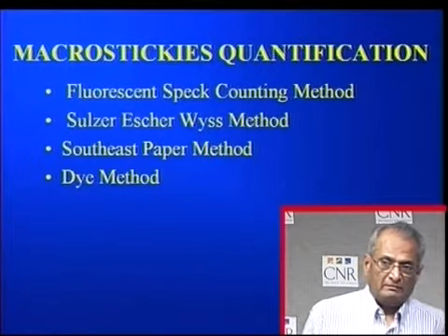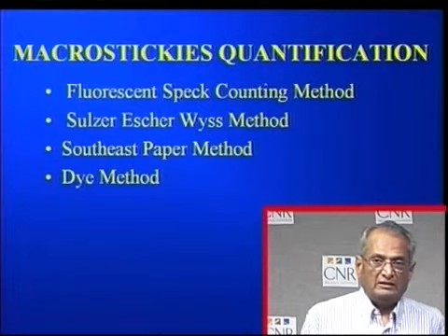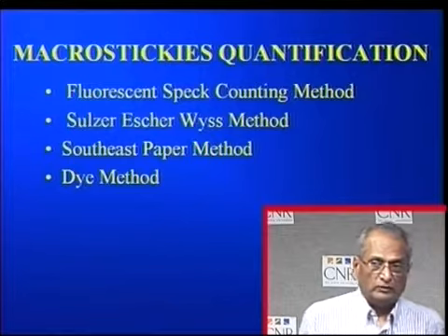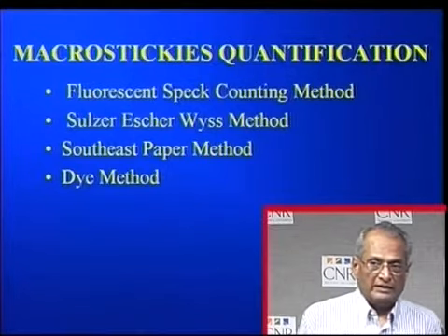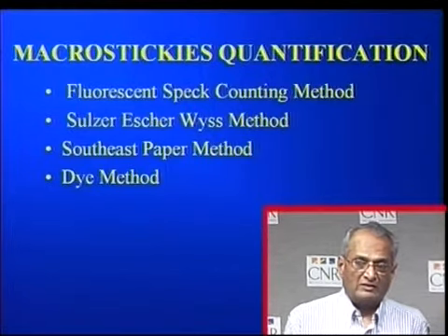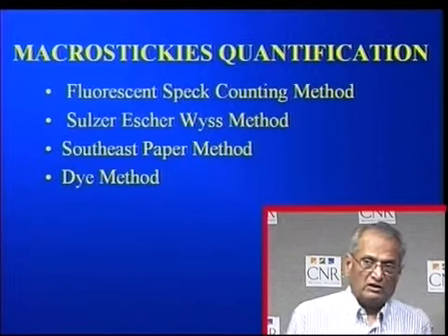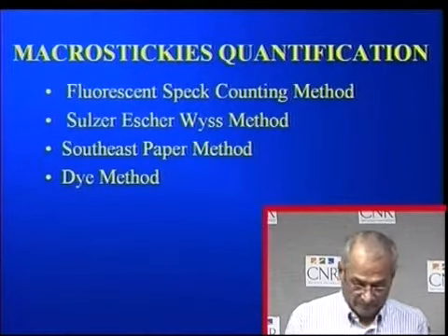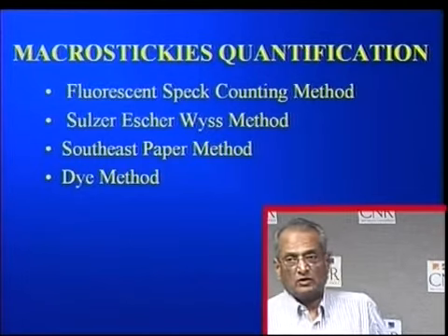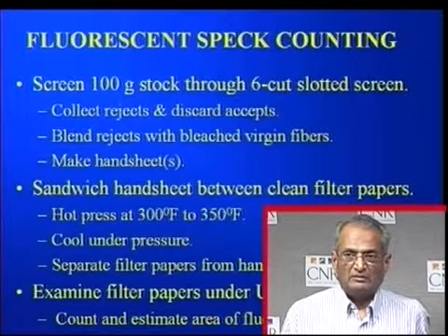Southeast Paper Mill in Dublin, Georgia, had a lot of complaints about the stickies in their newsprint. So they wanted to upgrade their de-inking system and wanted to install fine slotted screens. And so they developed a method, which we call the Southeast Paper method, to evaluate the performance of various screens. And then there are so-called various dye methods. So, just going through some of these methods briefly.